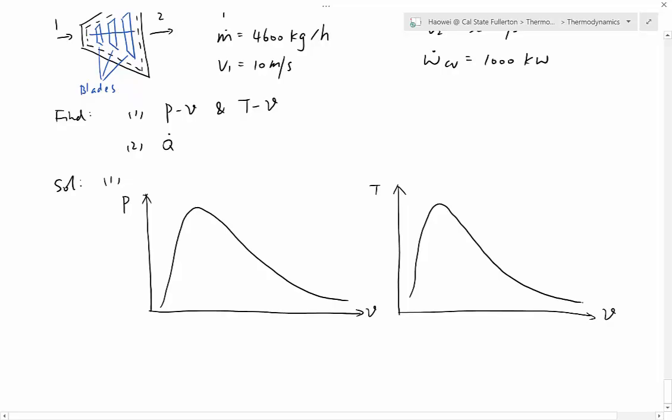Okay, so we always sketch the vapor dome first. And then, just like before, on the P versus nu diagram, we have constant temperature lines. How to sketch constant temperature lines? Curve down, straight, and curve down. And we'll sketch one more. One for T1, the other one for T2. And then on the T versus nu diagram, we sketch constant pressure lines. Curve up, straight, curve up, straight, and curve up.